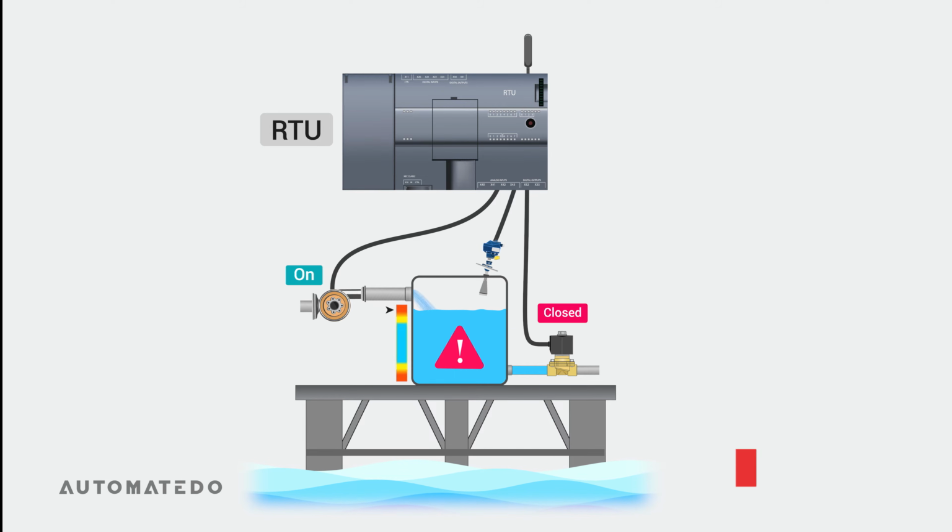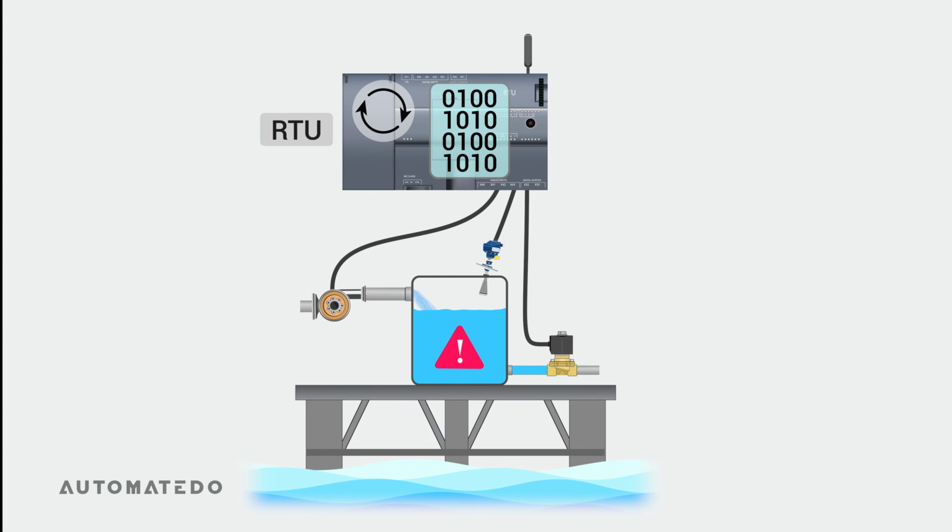An RTU enables the reliable monitoring of digital and analog parameters of various field equipment you have at remote sites. It acts as a local connection point to gather and collect measured data and information from connected sensors. The RTU performs data processing on the aggregated data, and as a result, the received raw data is scaled and translated into a transmittable format.